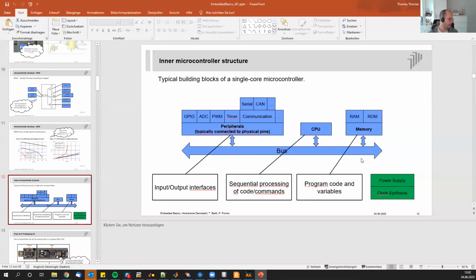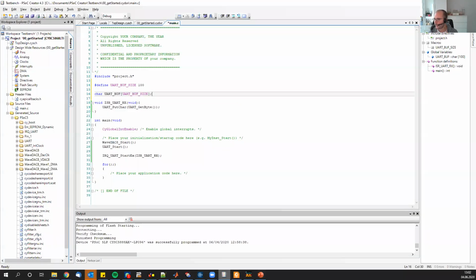So for example, I remember one of my first computers, an IBM compatible PC. When DMA became available, suddenly it was way faster to store something from disk or from CD-ROM to the hard drive, because it was simply bypassing the CPU. So the CPU was available for me to move around my mouse or do whatever while that stuff happened in the background. That's a little bit the idea here why we want to use it.